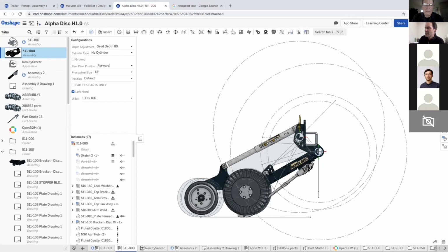The trick in SolidWorks is you create a layout part and then use it as your start part, right? But you only get one shot at it. If you screwed it up, you're screwed, because every part had a copy. You have to copy it each time as your start part. So that was another trick. So it's different, and I like the way that Onshape works now. I just wouldn't go back.